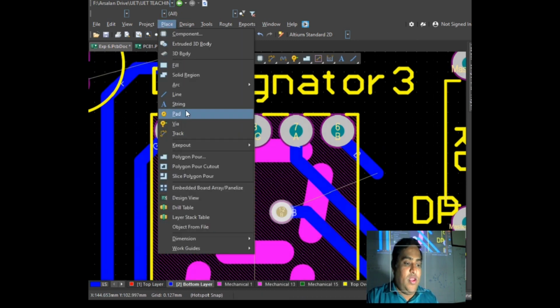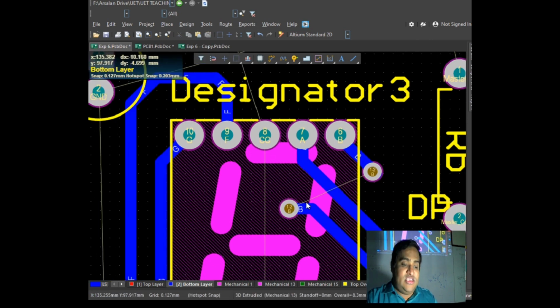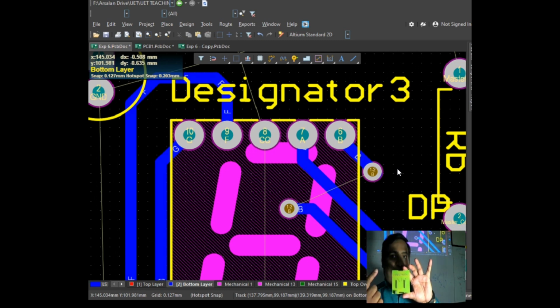Now what is a via here? A via is just going to be a jumper, which is just like this, as shown over there. You can see the jumper wires which are used on your Vero board. This is the jumper wire. Because it's a single layer PCB; if it was double layer, I could have moved it to the other layer and then brought it back. But this time, there are something like 1, 2, 3, 4, I guess 7 or 8 jumper wires. Now, the fewer the number of jumper wires, the better it is for you.